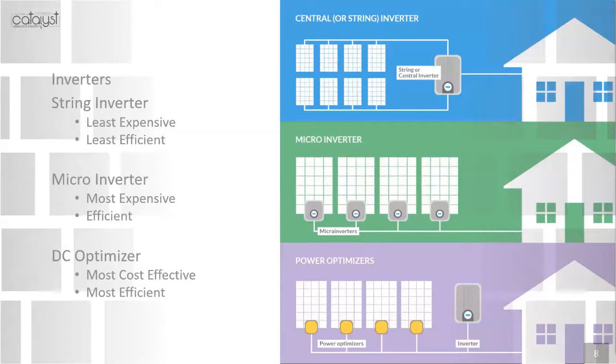So what became prevalent in the mid-2000s were microinverters. So move that DC to AC conversion from essentially the string, put it on the back side of the module, and now I end up with 2 technologies, one known as maximum power point tracking and the other known as module level electronics. And now on an install where I only have, say, 10 kilowatts, 30 panels, all of a sudden I'm not worried about the considerations I just talked about with the string inverter: shading, tolerances in manufacturing, degradation over time, or multi-roof angles, because each module is going to perform to its maximum, because now I'm wiring in parallel. It's not affected by the other module.